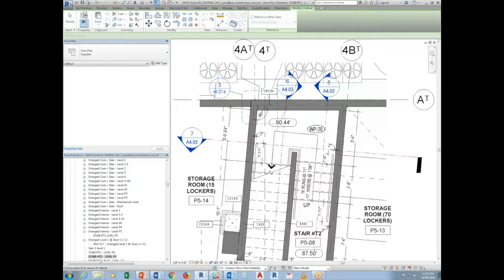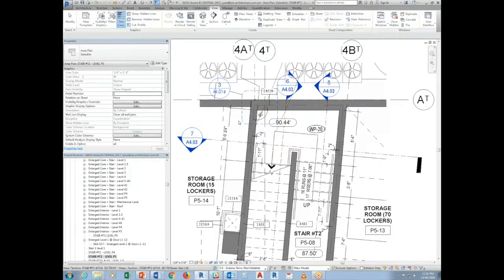Yes, that's correct. So this is why, when you're doing a lot of views, make sure you are very specific about what you want. Let's say, for example, in here I say townhouse 4, TH4 stairs. Then when you do a callout, you know that this is TH4, you just say TH4, and it will grab those two related stairs. The naming of the view is very important so that you can filter it very fast. Any questions so far?